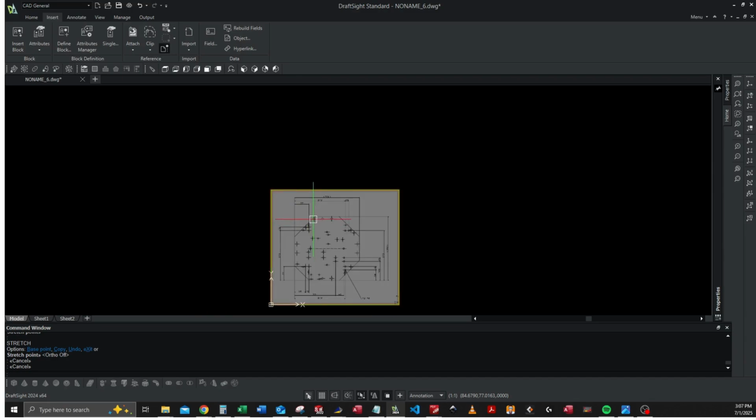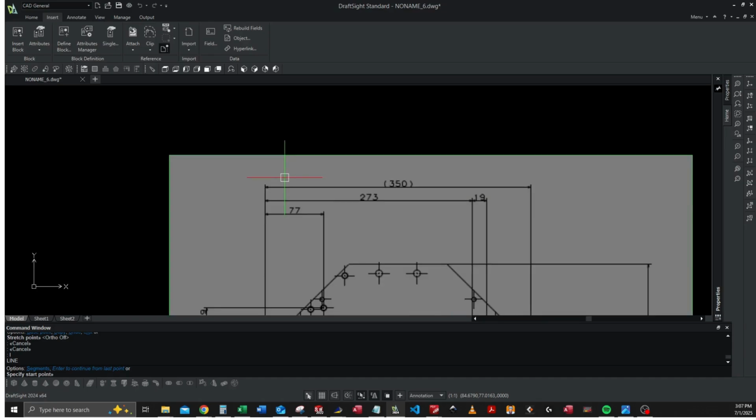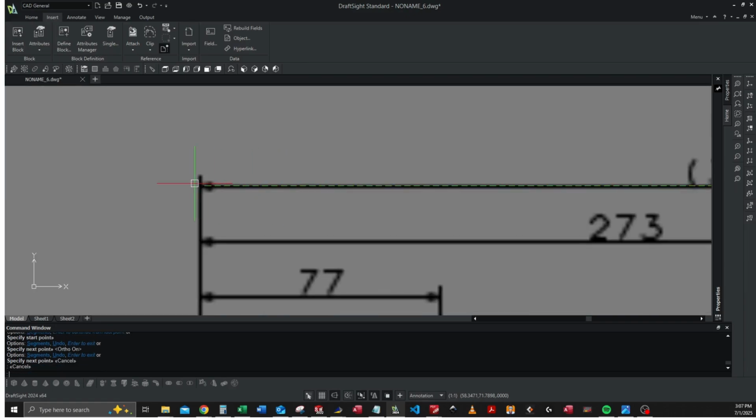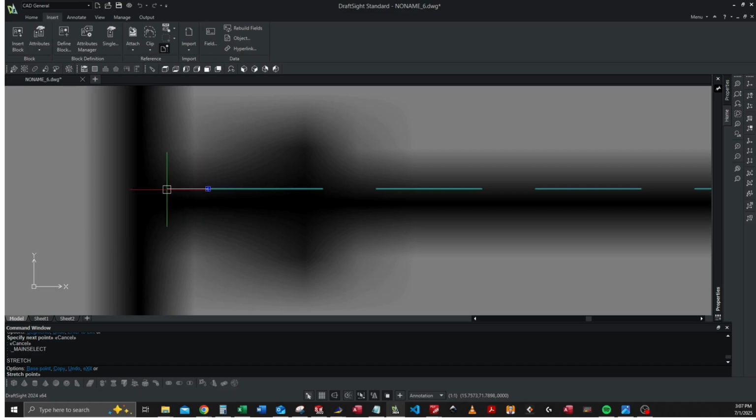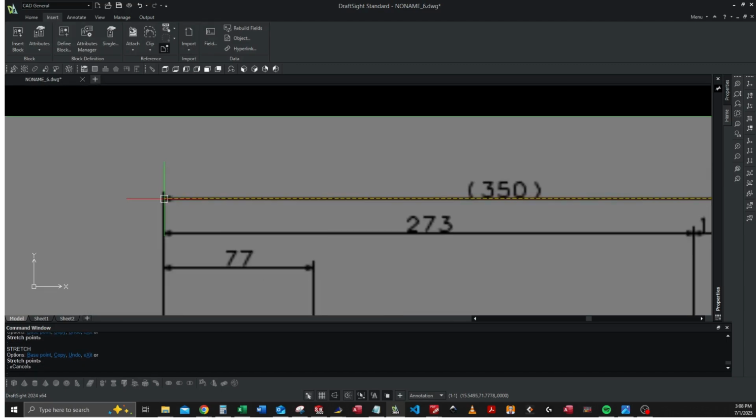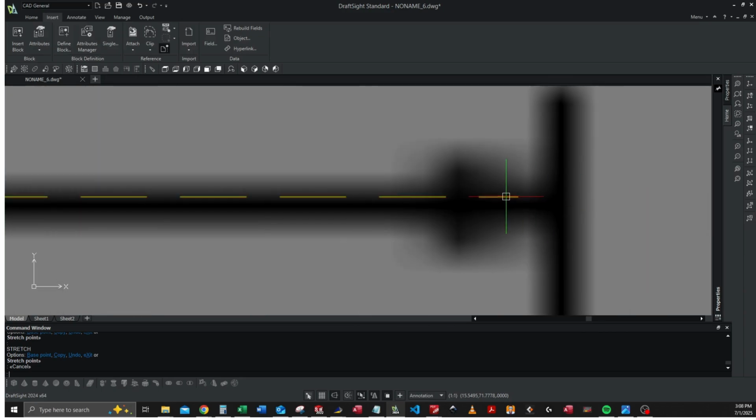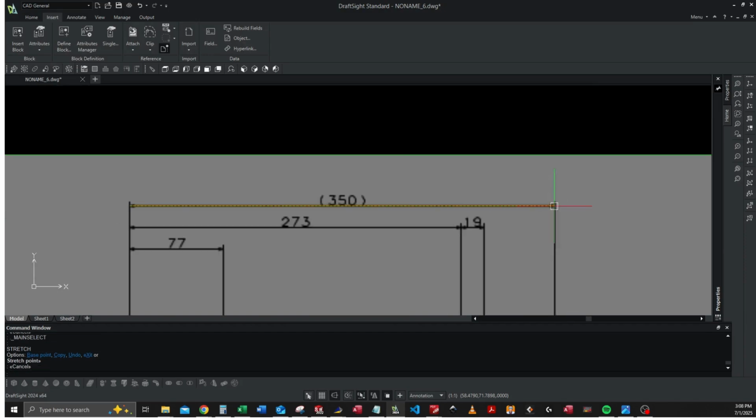Once you get that set, we'll need to draw a line so we can figure out how far off the scaling is. So just L spacebar or return. Draw this to my ortho back on, straight line across. You want to zoom in here, try to get this as close to the edge of the pixels as you can, as reasonably possible. Same thing on the other side, just drag it out. It looks like right about there.